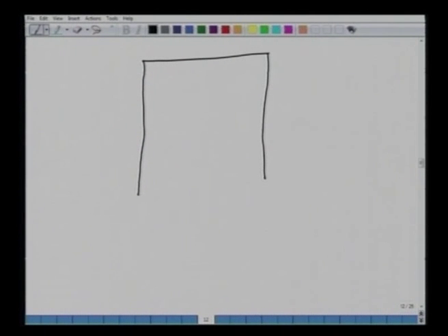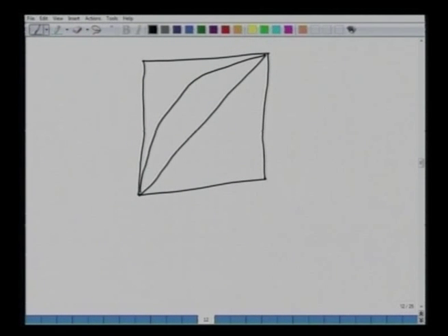All right. So we are trying to say here that if we have this equilibrium curve like this, let's say we have this operating line for the top column and we have the operating line for the second column, then we start drawing the trays, go to this operating line, and this is the Q line.